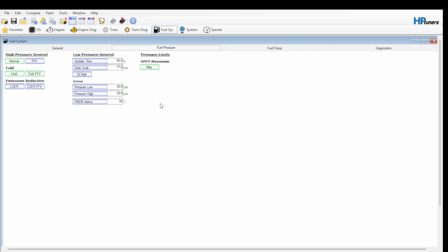Now, I'm not making that much torque because I don't have incredibly high flow turbos. I only have like 7% on stock. So I can make 500 horse with a boost cooler system or boost chiller system. But I can also make 590 foot-pounds of torque. But I'm going to pull fuel out of those torque ranges so the torque level is a little bit more linear and not just, you know, like a diesel, like I have it tuned right now.